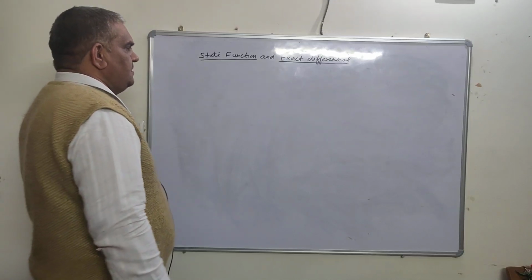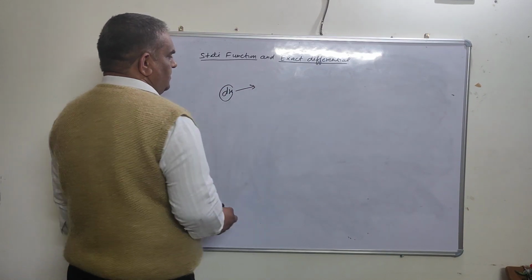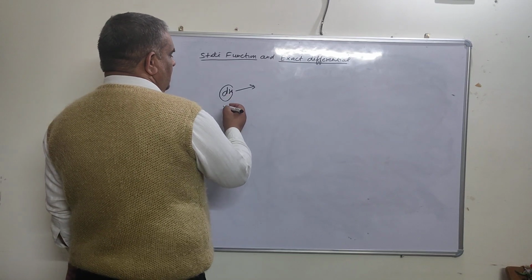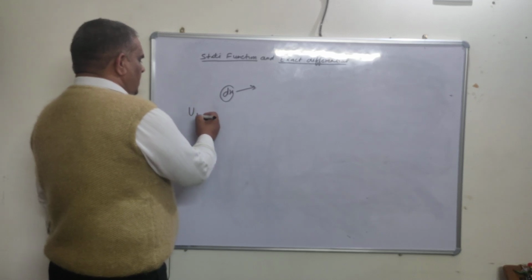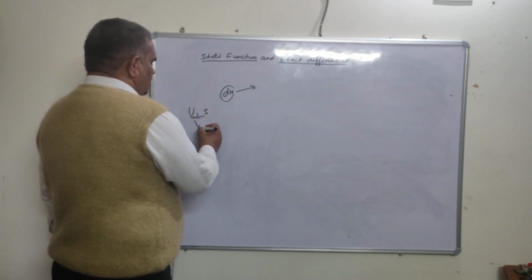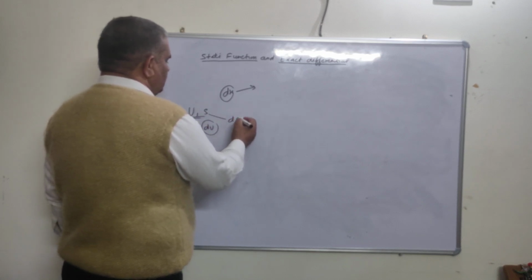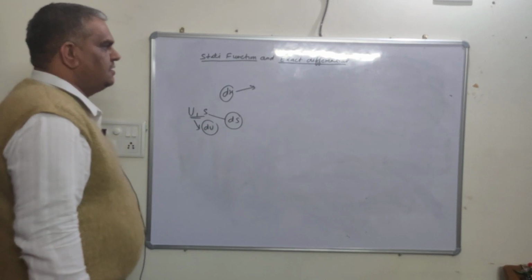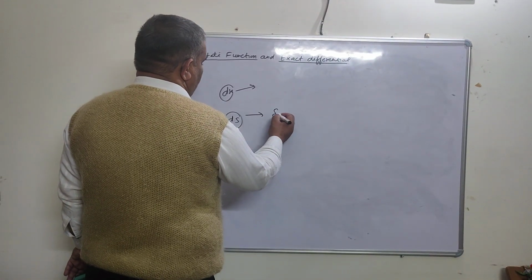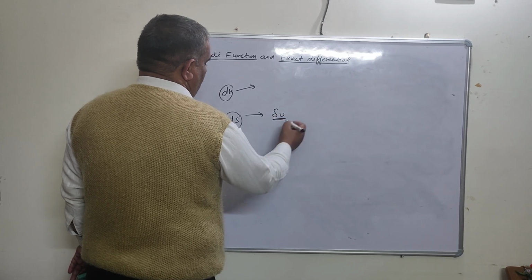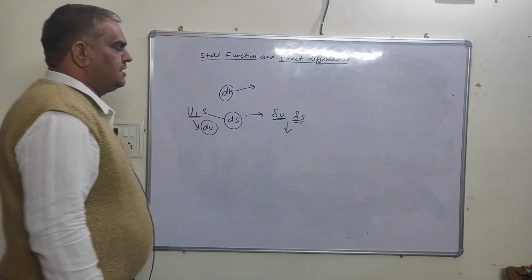Or exact differential: this dH is an exact differential, and symbolically we take U or entropy, this dU is also an exact differential, and this entropy dS is also an exact differential. Instead of this, delta u or delta s are inexact differentials.